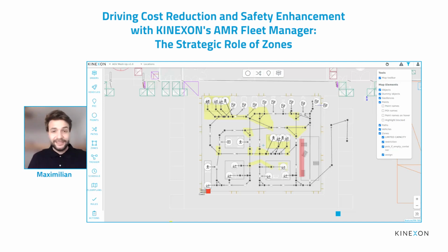Well, if you don't have a VDA 5050 interface, it means that you don't know too much about the robot. That means you don't have full control over the robot. And you sometimes cannot have it because the interface might not be available or cannot be built by the manufacturer. So what do we do in that scenario? In that scenario, we can put zones in front of intersections, and in front of those intersections it is possible that we set traffic lights again.